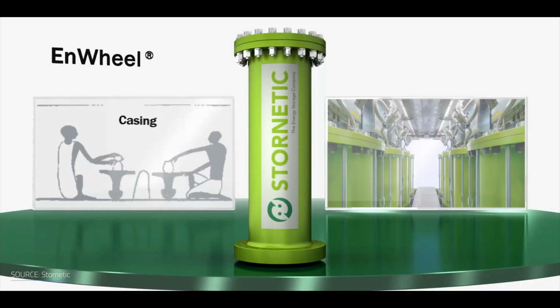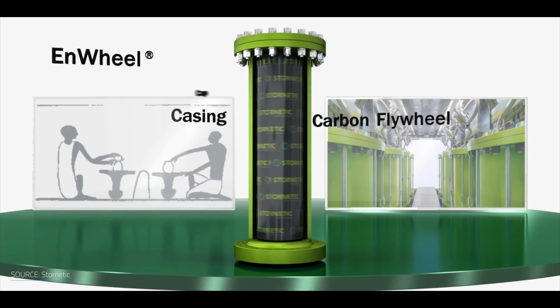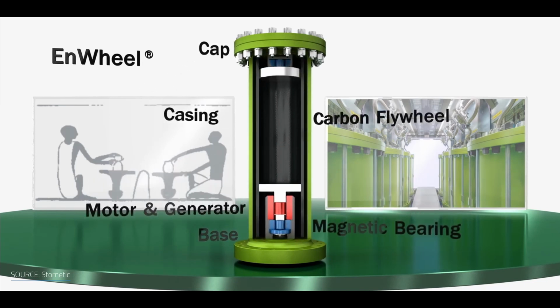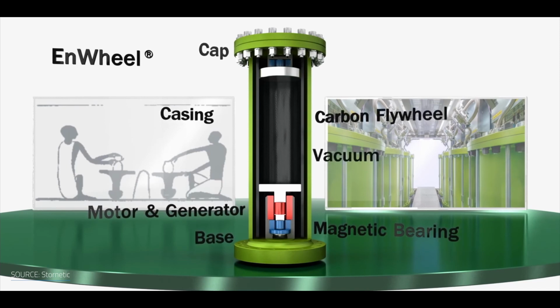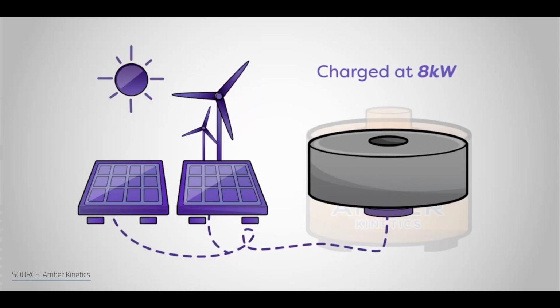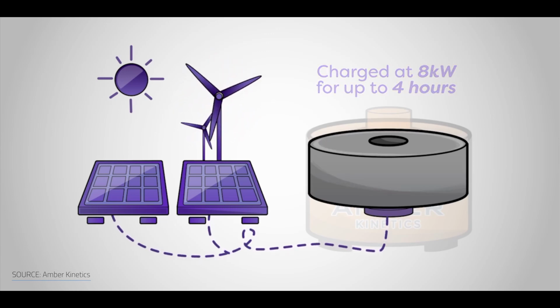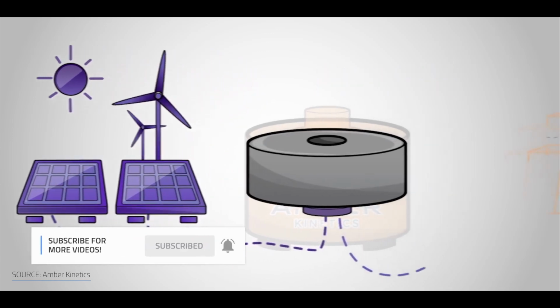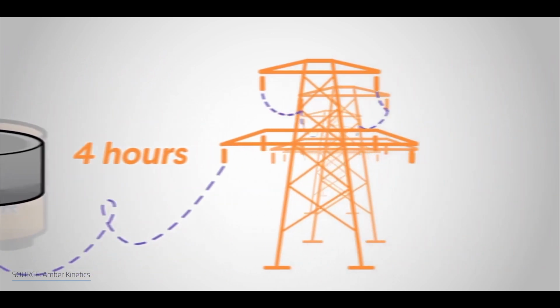Advanced flywheels are housed in a vacuum enclosure to reduce aerodynamic drag. They also have air or magnetic suspension bearing technology to reach those high speeds and are made of materials with high strength-to-weight ratios like carbon and fiberglass. In practice, flywheels have fast response to frequency changes, making it a good solution to stabilize grid frequency when unstable variations occur. In addition to that, they can be completely charged within a few milliseconds and have considerably longer lifetimes of about 20 years compared to other technologies.